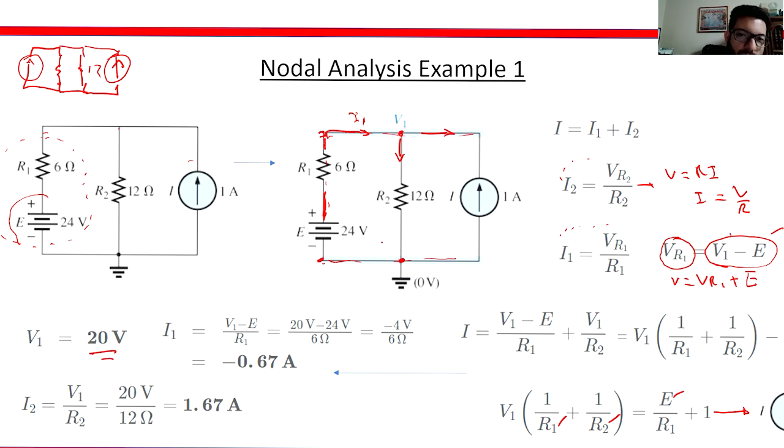And notice that since we had 2 independent nodes, we only had one equation, because the nodes here are not taken as nodes of analysis for the nodal analysis. In order to have a node, you have to have more than two branches bifurcating or breaking. That is just a voltage divider.